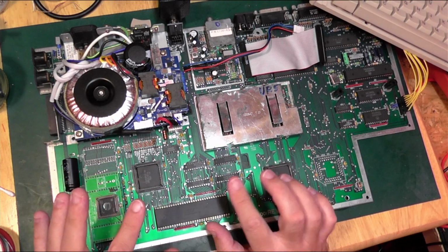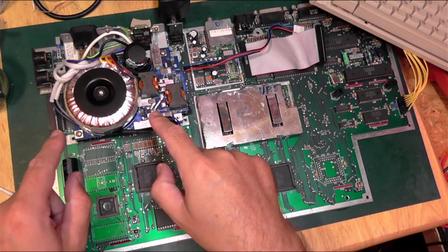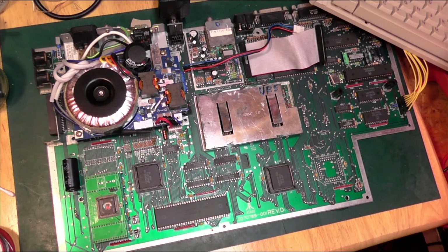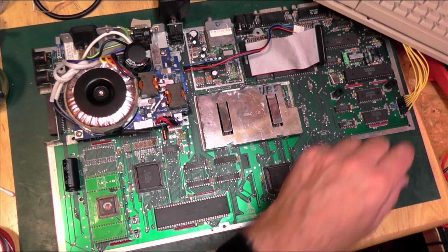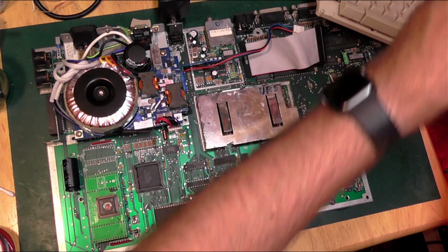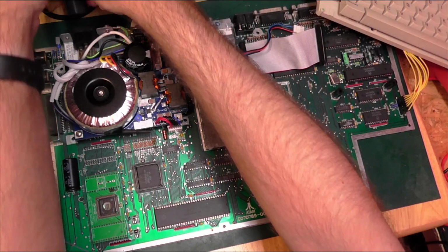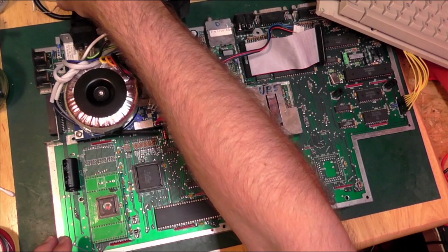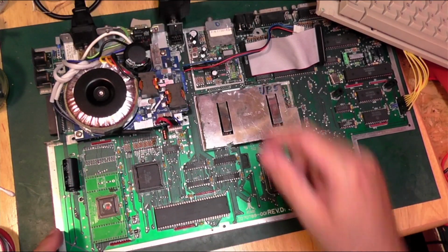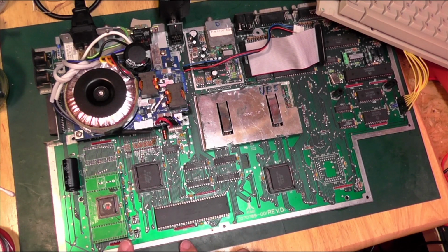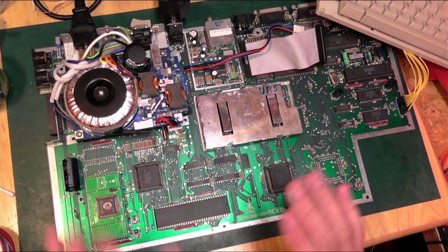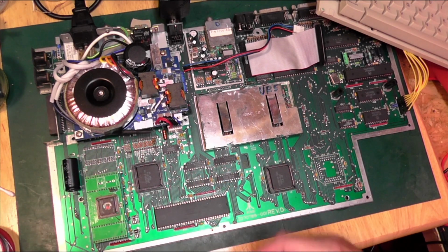Now, because I'm naturally pessimistic, I've decided to whack in the power supply and connect up the monitor again, and just make sure that we still have a booting machine after one, or a third, of the address lines have had the 2.2 pull-up applied. If it doesn't, we know we've got a problem. If it does, great, we'll continue with the rest of the lines.